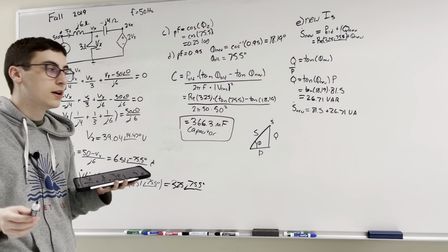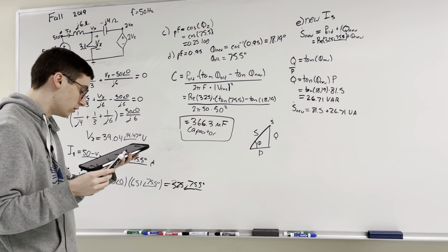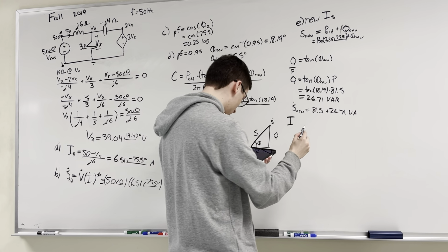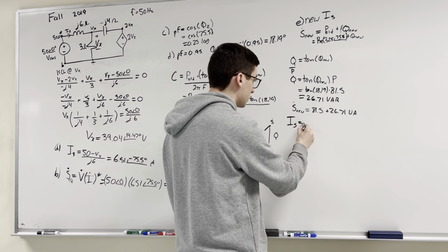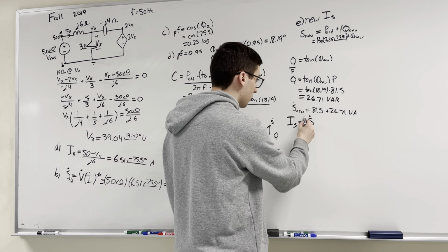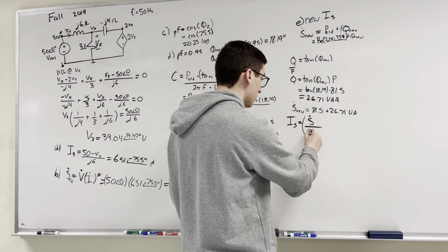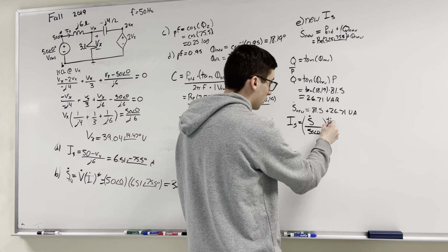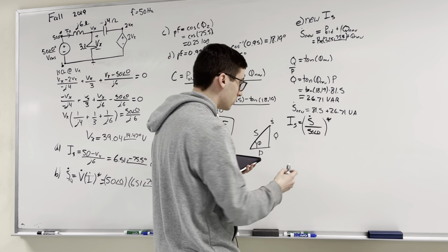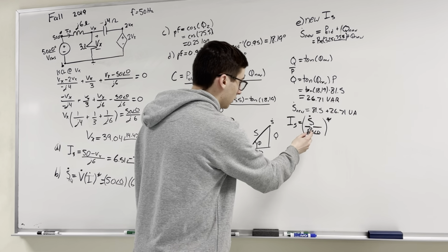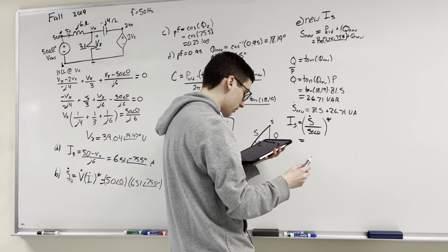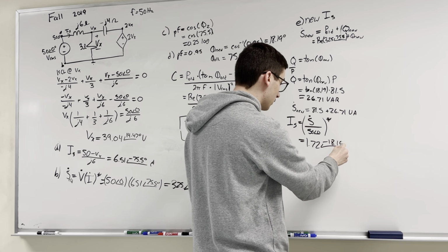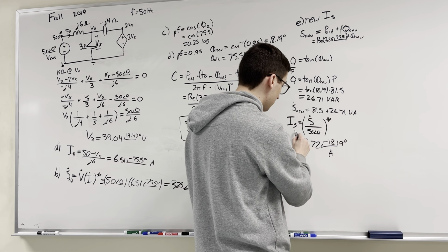We just calculated the new complex power, but now what we need to do is calculate the current. Using the formula, IS is equal to the complex power divided by the voltage, which is 50 with phase angle 0, all of that conjugated. So now you plug in S new for your complex number and 50, and you get 1.72 with a phase angle of negative 18.19 degrees amps.